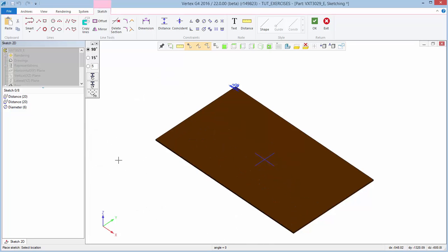The pattern is located in the sketching state. If the pattern is wrongly oriented, you can rotate it from the upper left-hand corner of the window. In the menu, you can change Rotate Step, which way you rotate it, or mirror the pattern. The pattern will be attached to the first hole, so the pattern needs to be rotated. In this case, choose Mirror Sketch, so the pattern is correctly with respect to the board and the first hole.